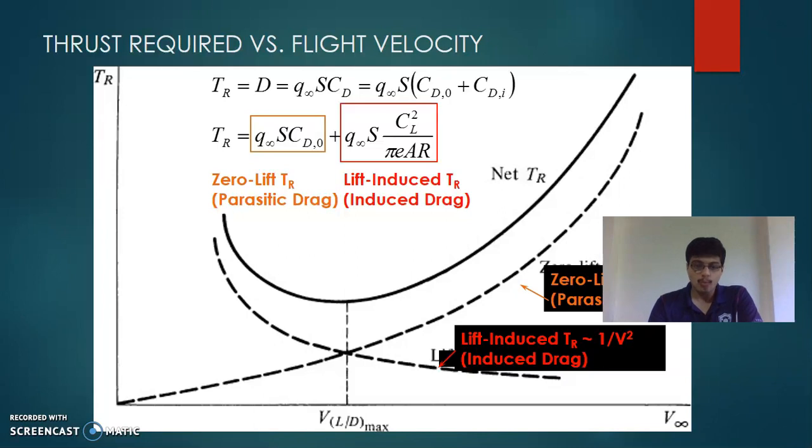Now, once looking at this, we also now know the lift induced thrust which computes. So what we are doing in this graph is simply resolving the thrust component into two parts. One, we say thrust because of drag, which is simply a function of the drag profile and induced drag profile, and thrust because of the lift. What does that mean? As you keep increasing velocity, the drag will ensure thrust goes up. But as you keep increasing velocity, the lift will keep bringing it down. And hence, when the drag wins, the thrust requirement wins. That's the simple explanation.